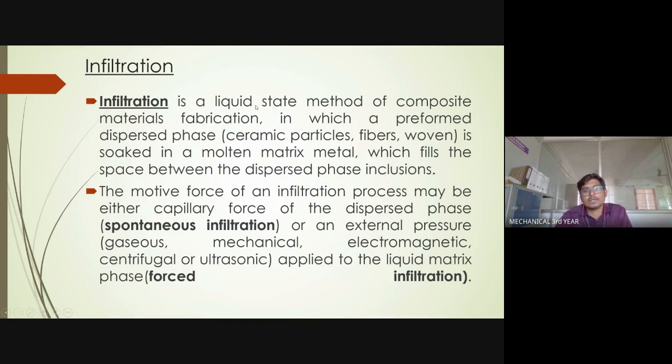Okay, let me read this point again. Infiltration is a liquid state method of composite material fabrication, in which a preformed dispersed phase, maybe ceramic particles, fibers, or woven, is soaked in a molten metal matrix. So what we are going to do is the dispersed phase of reinforcement is getting soaked into a metal matrix, which fills the space between the dispersed phase inclusion. Okay, we'll try to understand with the help of diagrams in the next slide.